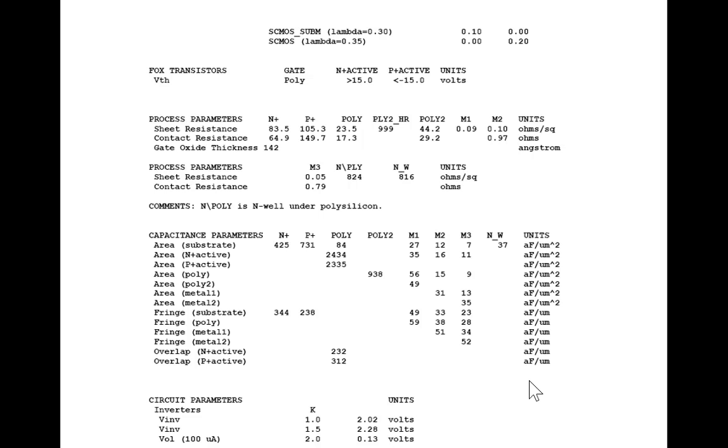The units for those capacitances are absurdly small. How do they get those values? The question is, can you measure them? Well, two things. First of all, you know the epsilon. You can use a scanning electron microscope and measure the thickness of the layer, and you can calculate what it would be. If you want to measure them, and you have an area that's really, really small, there are clever circuits that can actually infer what these capacitors are, even though they're so small.